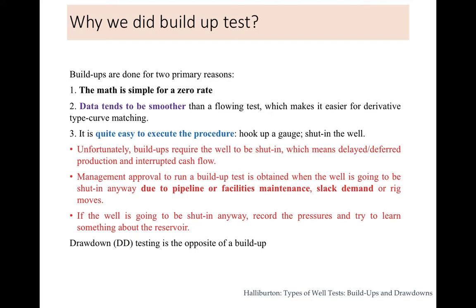Number three, it is quite easy to execute the procedure, right? You hook up the gauge, shut in the well, place the tool at the bottom hole, and you can record. So it will not give you much pain in recording and gauging the data. Overall it makes the build-up test quite useful.